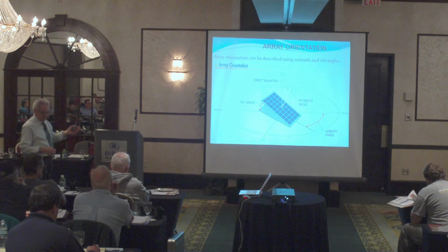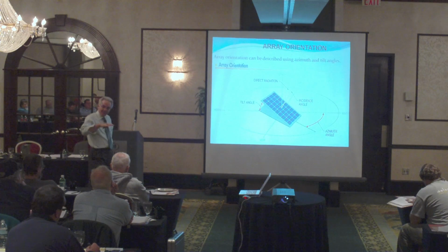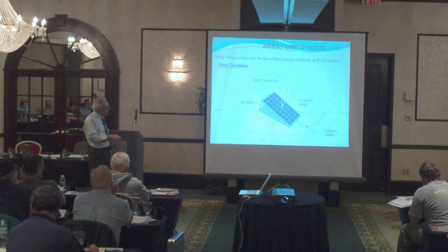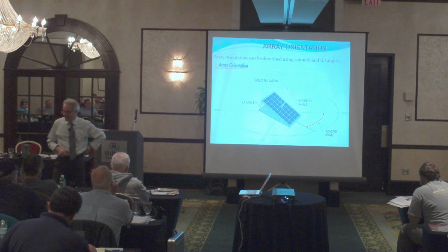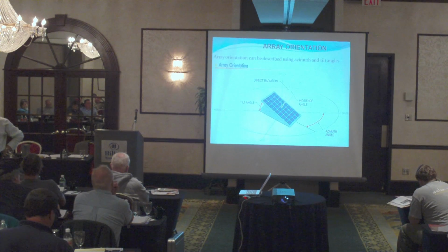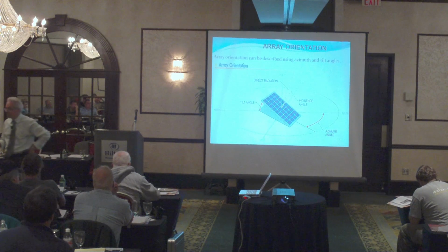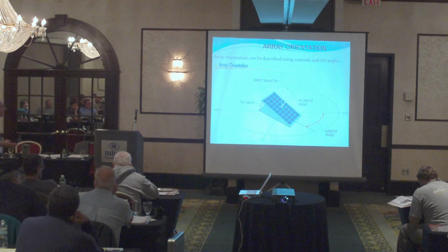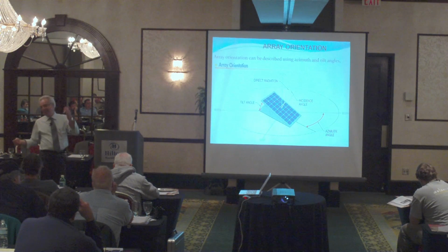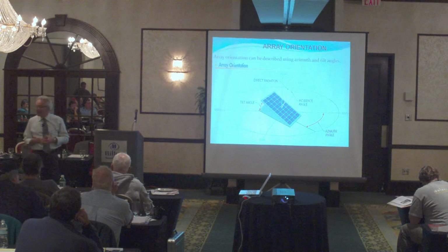Now, ideally what I like to do is take the panel and make it follow the sun's position, so at all points in time I have the sun perpendicular to the panel. Can I do that? Certainly, if you have a tracking system, so I can track for maximum power output. Since I don't have it, what do you practically do? Find the best spot. If this side of the house is facing south, just stick a panel there, whatever the direction is.